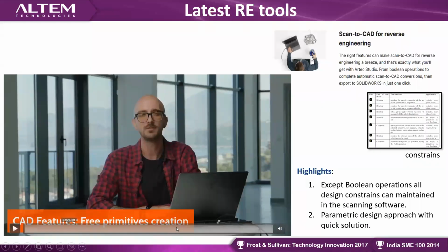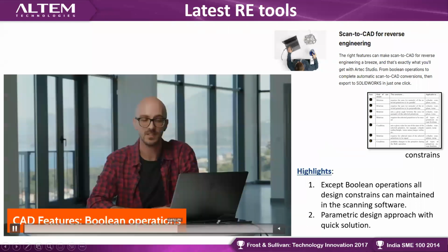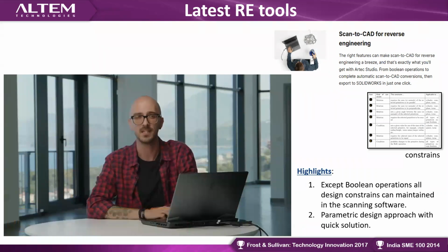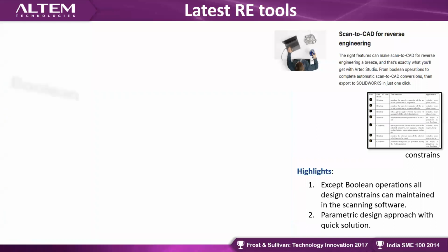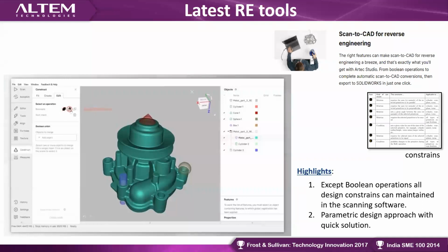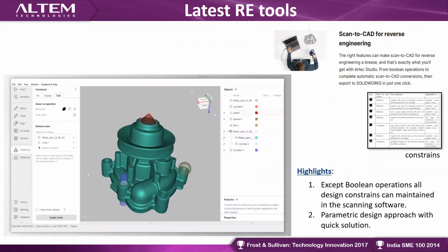What I was telling is about these Boolean operations. Whenever we create a new design in design software, first we extrude in some direction, and other dimensions or features in some different X and Y direction. Later on, we either merge the data, or if you want to make it a negative, we subtract the data, correct? And if you want to check an intersection, we also do that. So here it's the same thing, whatever primitives we are creating, of course, that is a CAD model only. The same CAD models can be used to edit the scan data, which is very unique here.